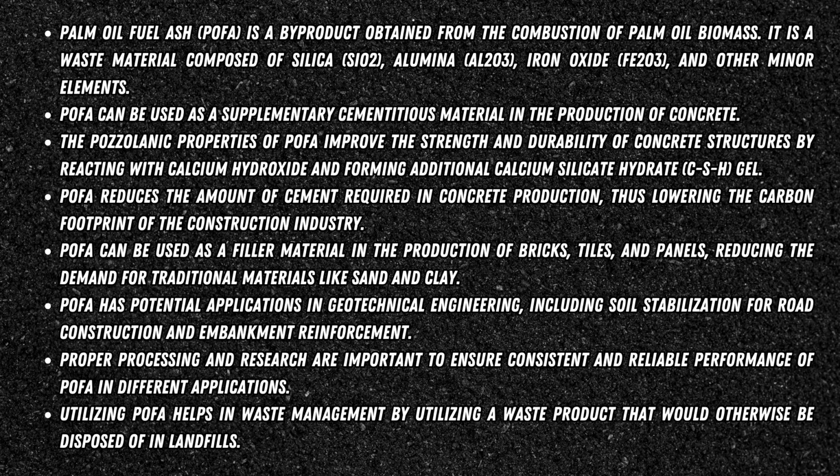POFA has potential applications in geotechnical engineering, including soil stabilization for road construction and embankment reinforcement. Proper processing and research are important to ensure consistent and reliable performance of POFA in different applications. Utilizing POFA helps in waste management by using a waste product that would otherwise be disposed of in landfills.